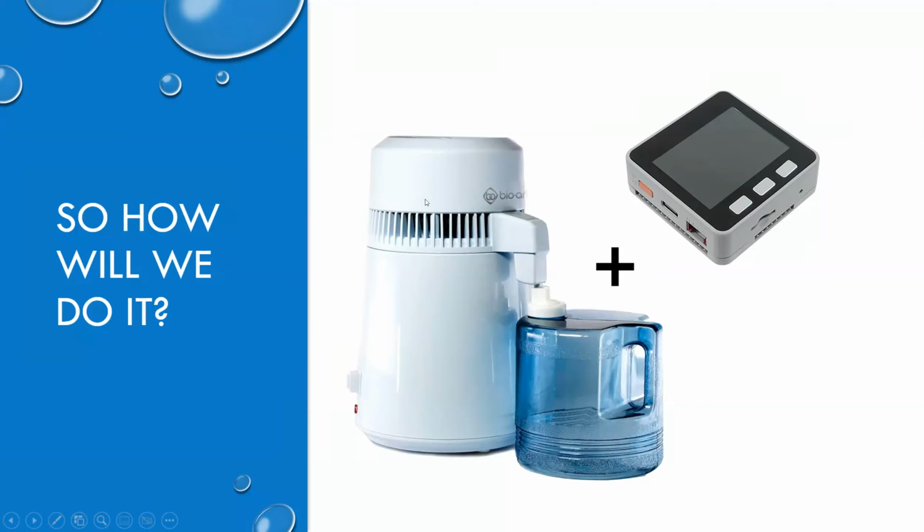Now, what we want to do is keep the fan going no matter what, in order to keep the condenser cool. But we will be turning the heater on and off as required to maintain the temperature. Because of that, it's mainly the heater that is connected to the relay, and not the condenser fan.